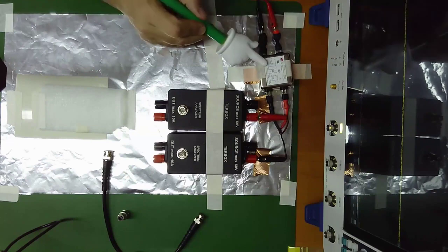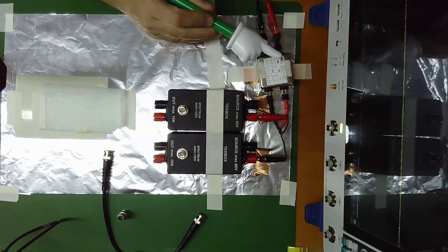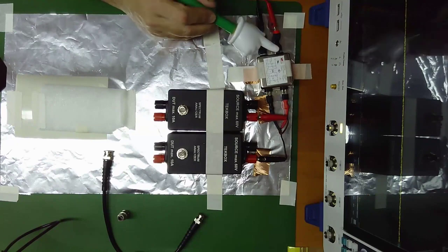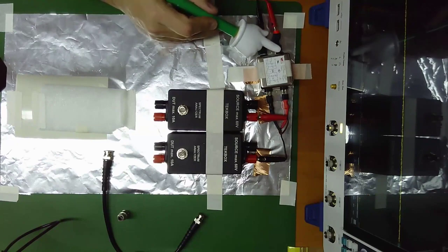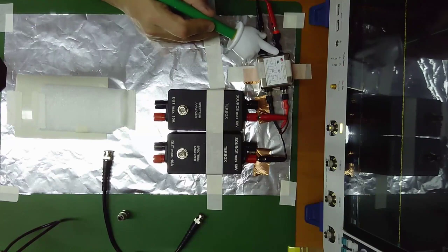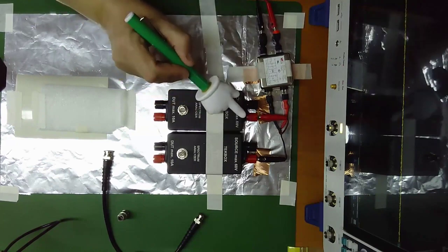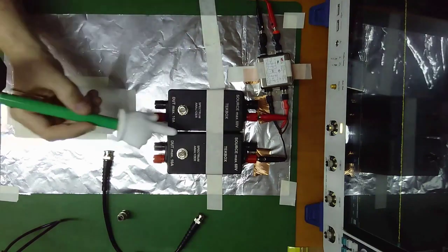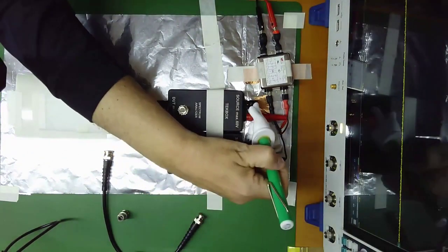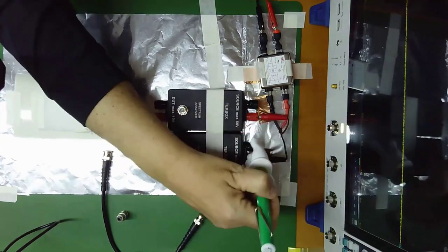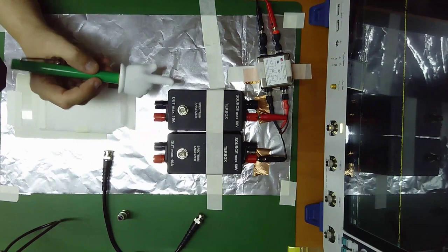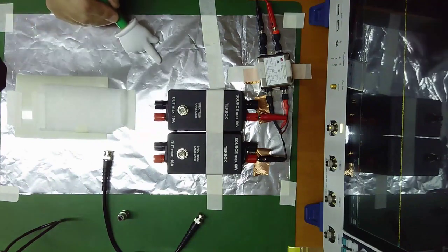This is a filter that is used to be sure that no noise is coming from the power supply. This is especially important if you are using a switching mode power supply in your laboratory. So the power we apply in our setup is as clean as possible. The negative terminals of the LISNs are connected directly with 2 short and wide connectors to the ground plane. The ground plane is represented with this aluminum foil.